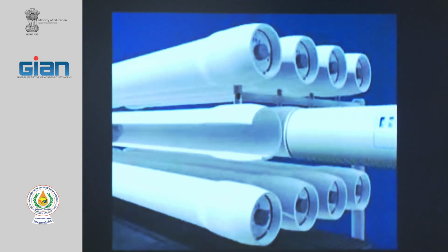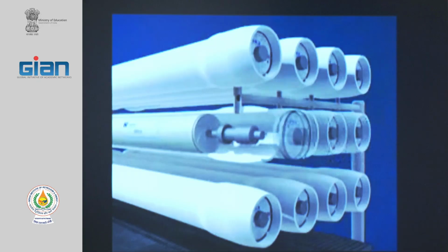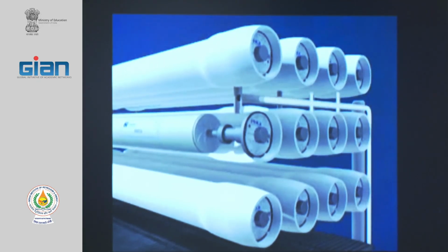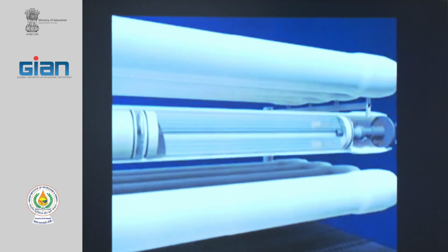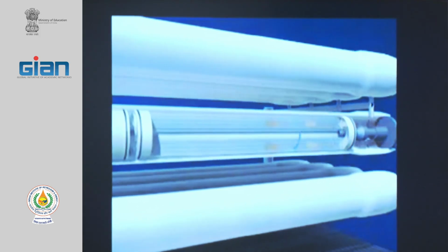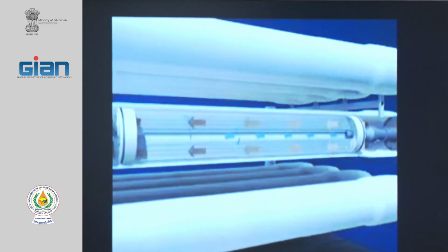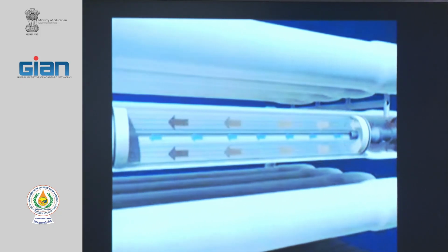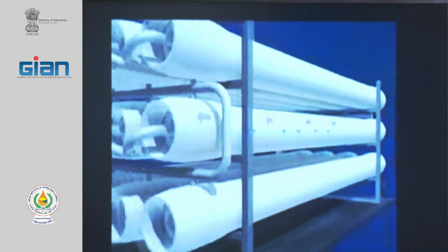Hydronautics spiral wound elements can then be loaded into pressure vessels. Modules are interconnected with additional elements to complete a number of vessels to design specifications. Once the end adapter is connected to the last element and the pressure vessel is complete, concentrate feed water of the first module goes to the second module. The feed water that does not permeate goes on, and the permeate collects in the central tube.